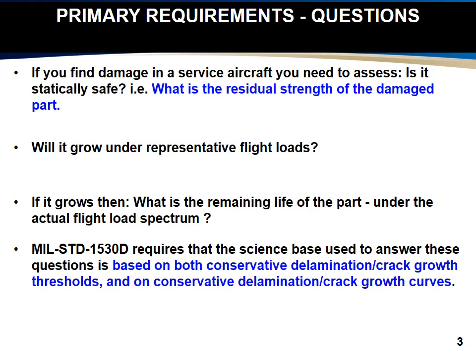If you find damage in a service aircraft, you need to ask, is it statically safe? What's the residual strength of the damaged part? Will it grow under representative flight loads? If it grows, what's the remaining life of the part under the actual flight load spectrum? MIL Standard 1530D requires that the science base used to answer these questions is based both on conservative delamination, crack growth thresholds, and on conservative delamination, crack growth curves.